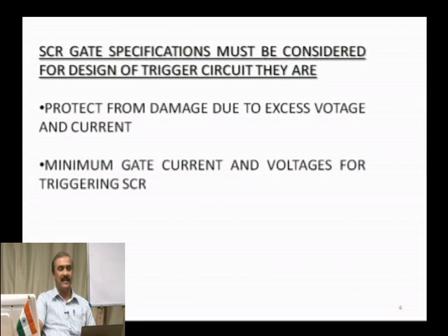See, SCR gate specification must be considered for design of the trigger circuit. So, what are the specifications that are very important before you design a gate circuit? Simply, it is not a simple power supply with a resistance circuit. You need to know the levels of voltage and current to be applied to the gate circuit safely, so that your SCR turns on very safely.